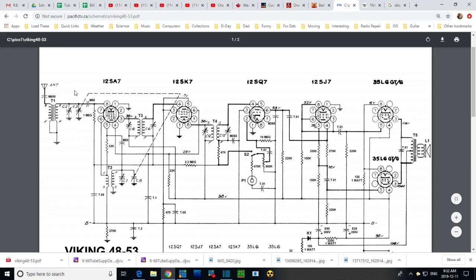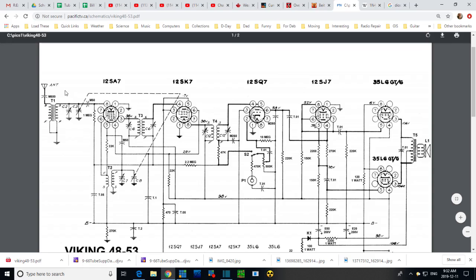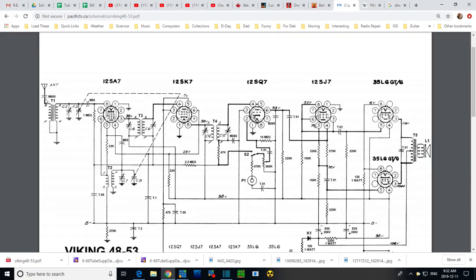So we come here and we ask ourselves, how much of that special tuning is there in the front end of this radio to drive away unwanted adjacent signals? So there's some tuning right here with the antenna itself and this coil. Don't know if that's effective. This capacitor may be there to help with that. Don't know. Well, it just says M5500, so it's a 500 picofarad capacitor. Not sure. Who knows how many turns are in this winding and all that kind of stuff. But there may be some.